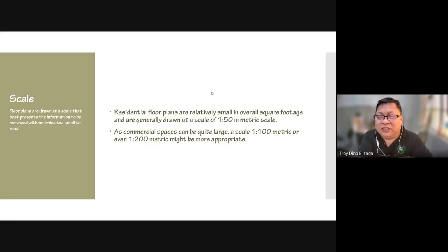There are engineers and some architects who draw the floor plan at 1:100. Even for a construction drawing. Maybe this is good if the house is very simple. A commercial building can have the 1:100 scale, or even the larger 1:200 scale, no?